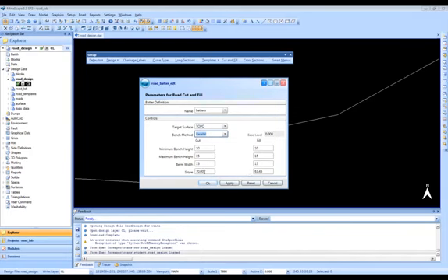And this is typically on a slope, basically undisturbed material, perhaps you're cutting into rock, whatever. You might be able to hold a steeper angle on that side slope than if you were in a fill situation. So here's where you can take care of that.